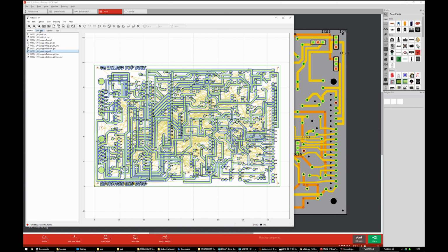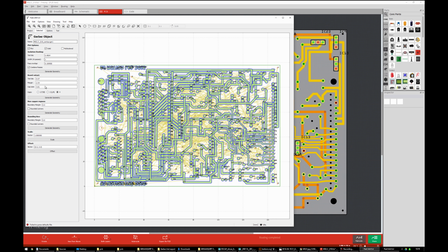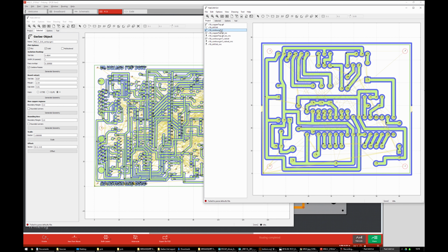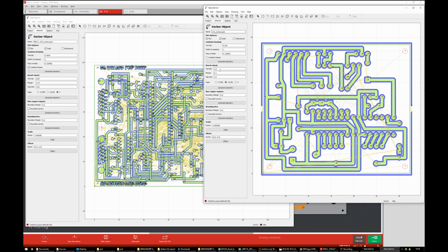So select the contour. Board cutout is what we need to do. Tool diameter. What is the tool diameter? It's a cone, so it's going to be deep. I guess it doesn't really matter as long as it's within the ballpark. And I'm going to refer back to my known working project. Contour cutout. Oh no, GM1. Contour GM1, yes. Here we go, board cutout.